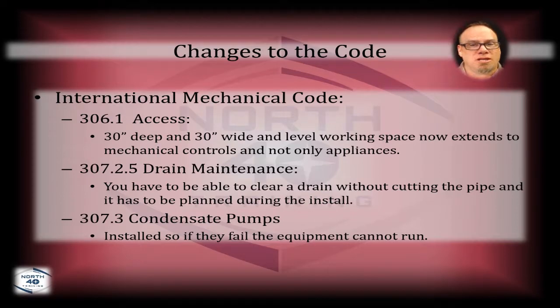And in addition to that, you're required to put in a secondary or overflow drain if the pan permits that, if there's actually a connection for that. So just within the last couple of code cycles, we've added some complexity to just putting in a normal condensate drain. So when you think about it, previously we've added requirements for size. Okay, it doesn't mean that you can't use some of the traditional methods.